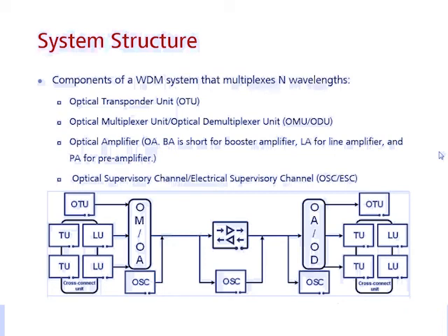But you know, we must have one unit to help us realize this process. That is the optical multiplexer unit, OMU. OMU can help us multiplex all the wavelengths into the same fiber. Okay, because the OMU is a very big unit, during this process it will have a very high attenuation, I mean insertion loss, for your service.